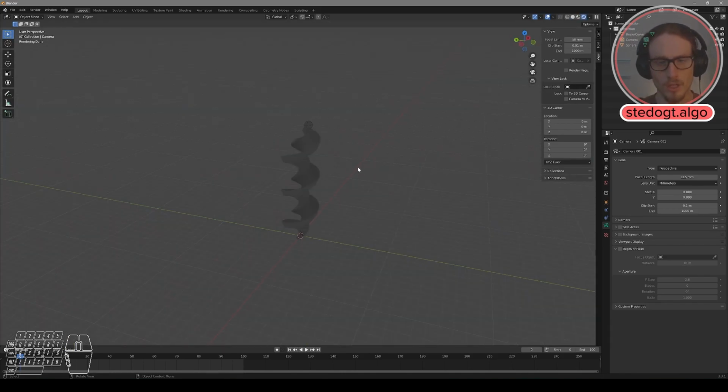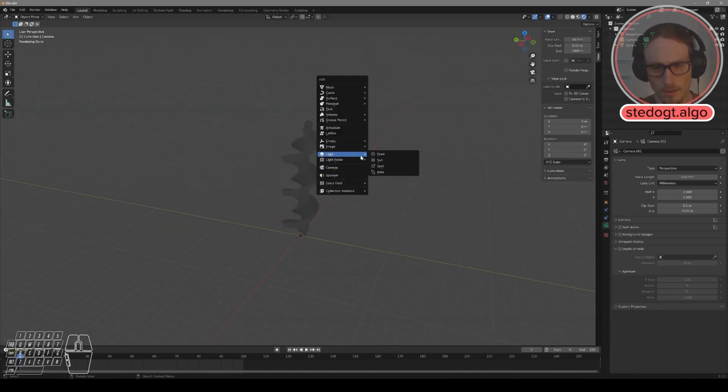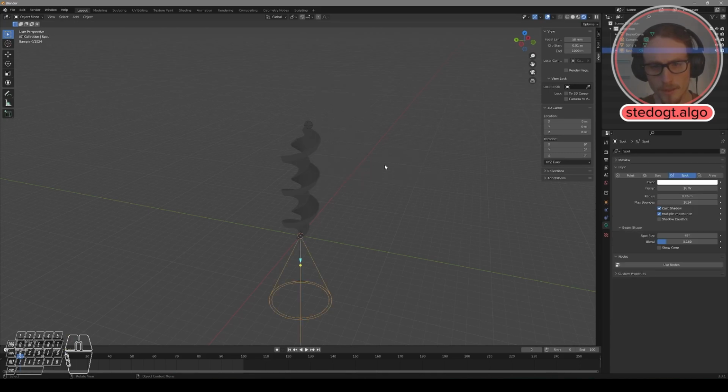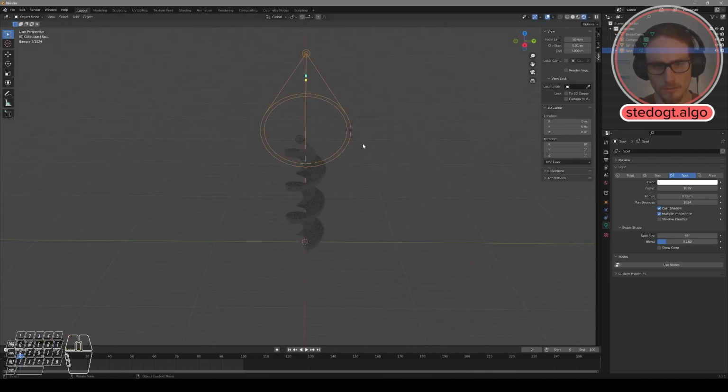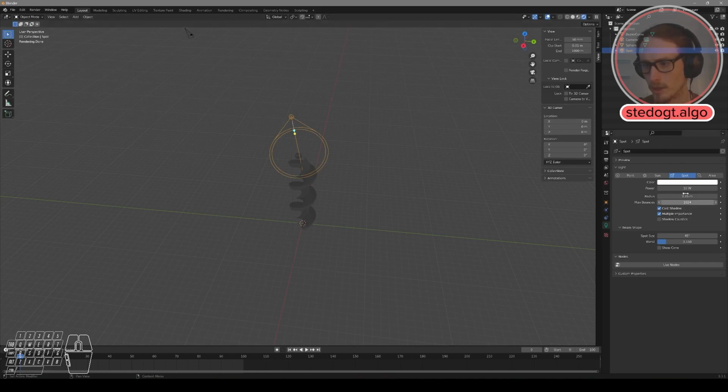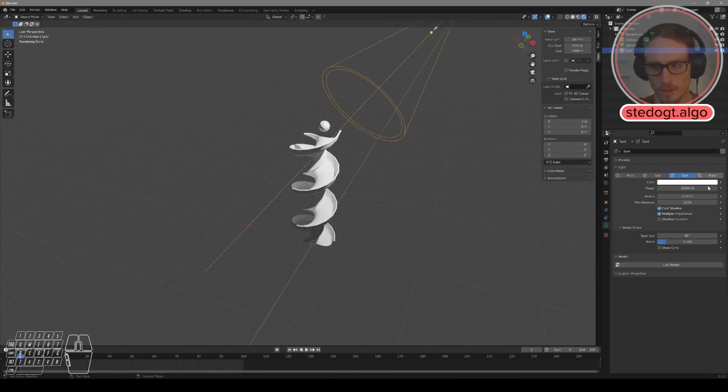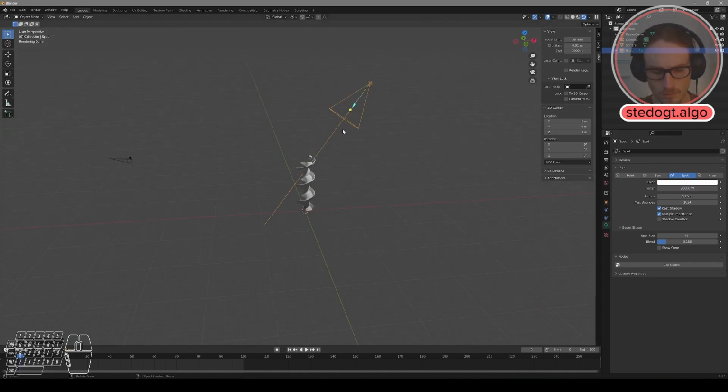So we currently don't have any light in our scene. We want to Shift A to add a light, and I'm going to add a spotlight. G to grab, and R to rotate. We select that light, we can adjust the light power. I'll take it up to 30,000 right now. There we can see our scene is now lit. Maybe let's bring it down to 20,000. I'm going to Shift D to duplicate my light and place it over here.